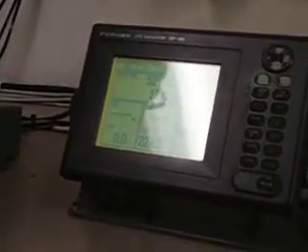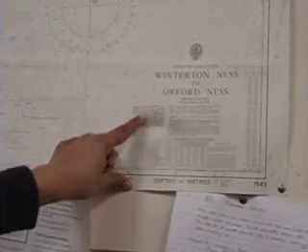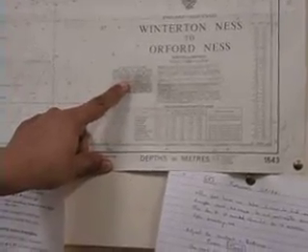There are 11 questions on the practical. You need to know the answer to this question, how to do it: extract geodetic data from the chart and enter the value into the GPS. Now suppose this chart is showing a satellite derived position. Positions obtained from satellite navigation systems are normally referred to the WGS datum, World Geodetic System. Such a position should be moved 0.03 minutes southward and 0.11 minutes eastward to agree with this chart.